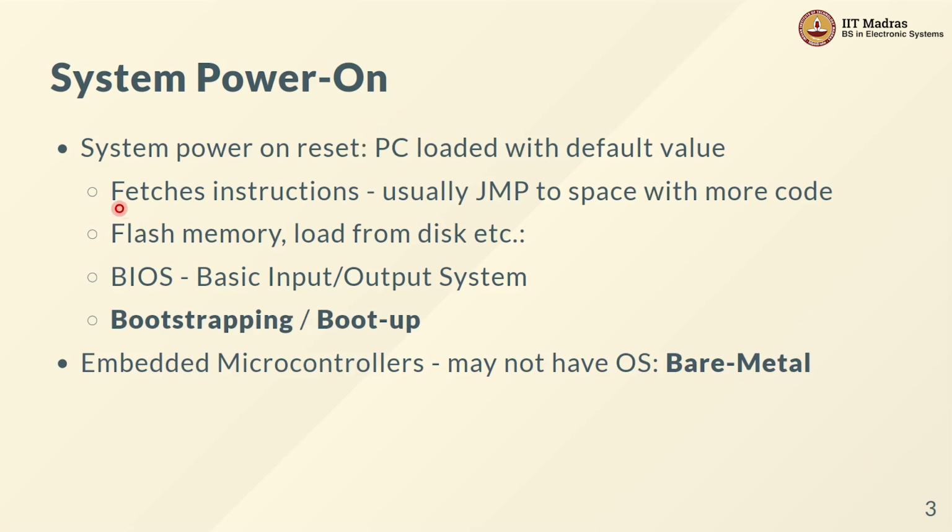So this fetching of instructions means that if I can set up my hardware in such a way that whatever is connected at the memory location corresponding to PC gives me back valid instructions, they will get executed. If it gives me back invalid instructions, the CPU will either go into an error state or it will ignore those and continue just incrementing PC, depending on how the CPU has been built or designed, of course.